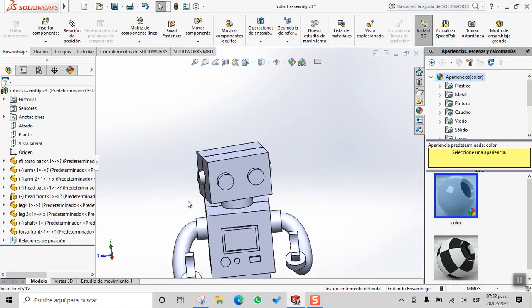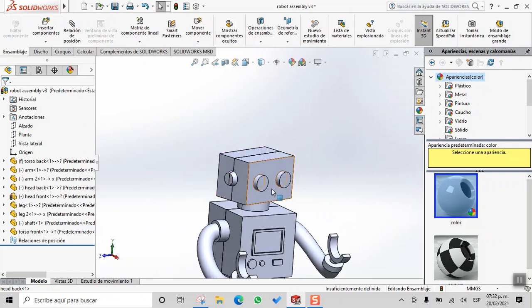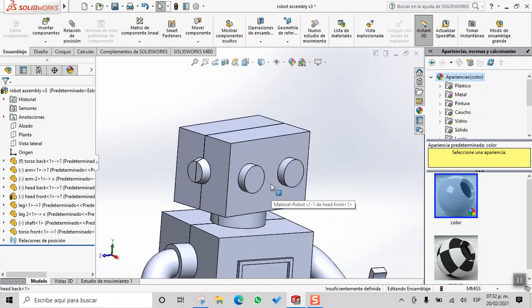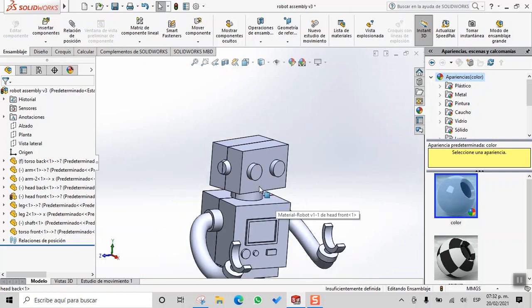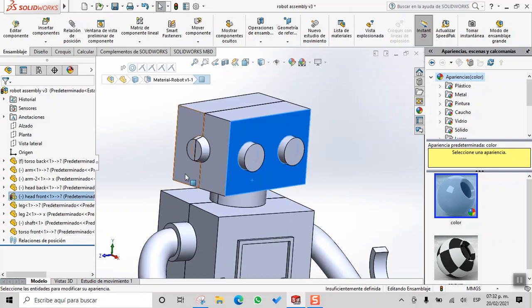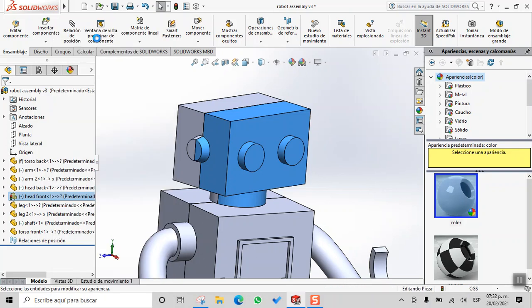And so the idea is that I will add a screw right here and I will add a pole in the front to be able to hold the part. Also, I will add some lips right here to avoid the part from twisting after the assembly. Okay, so I will click here and let's see if I can right click and open the part, and we can find that command here, edit part.